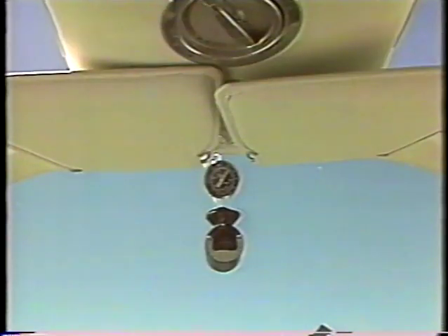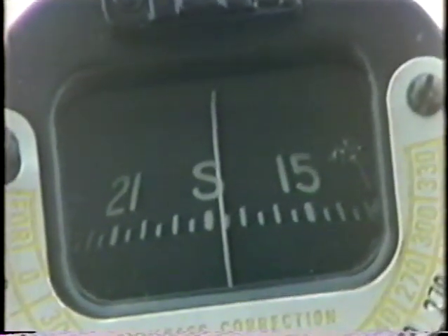All of the instruments we've discussed, except the inclinometer, have required some external source of power. The magnetic compass and the outside air temperature gauge are self-contained instruments and do not require any external power source. The magnetic compass is usually mounted above the instrument panel and is the only instrument that provides the pilot with actual directional information relative to the Earth.